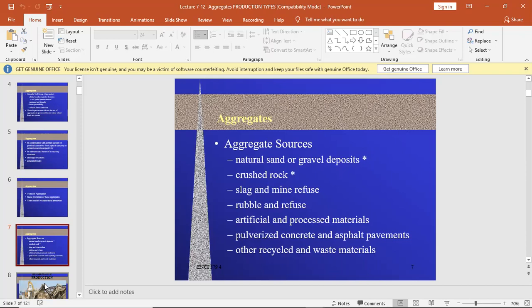But before I go ahead, let me tell you, no one has ever replaced natural aggregate 100%. The maximum people have gone is 30%. Again, there are reservations, but based on the knowledge and data I have, I think 15% is okay.